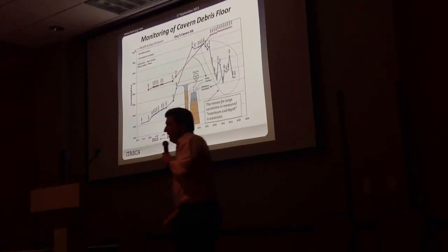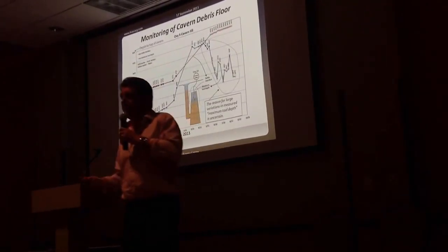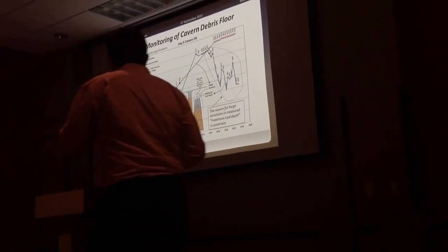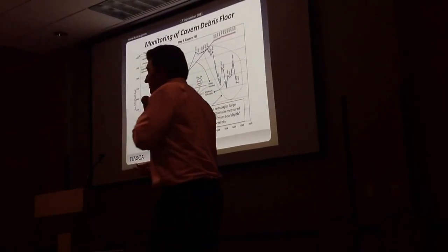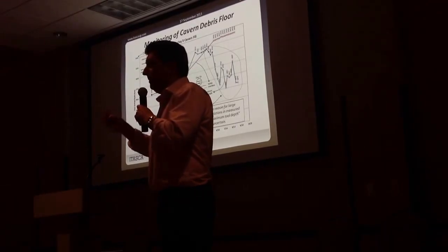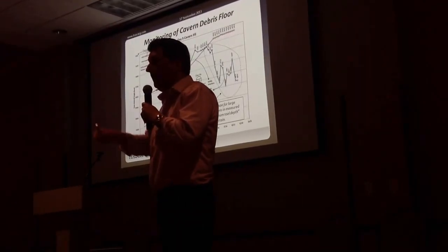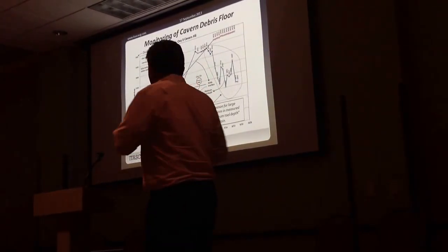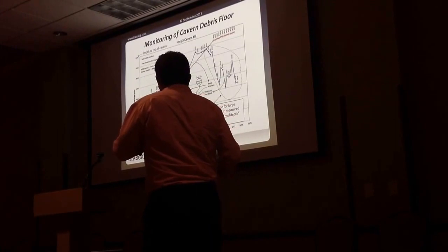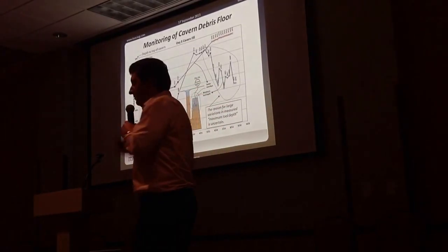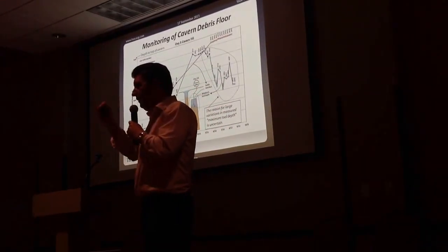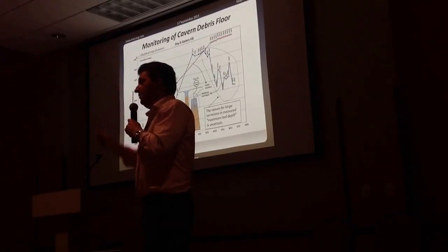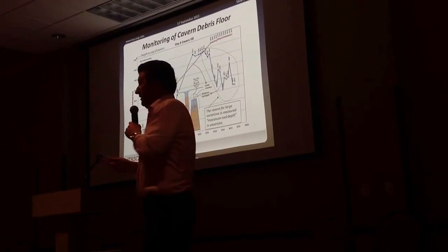And where we see this effect is in these tag measurements that have been routinely taken in the Oxy 3A well. What's been done here is that a metal weight has been put on the end of a wire line and run down the 3A well, 3,500 feet into the cavern. And that tag goes into the material that's within the cavern. What it first sees is this very loose, sloppy mud at the top. And eventually it hits something that's much more solid.